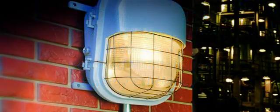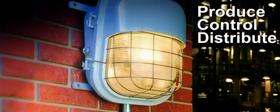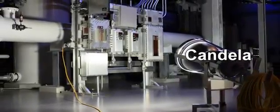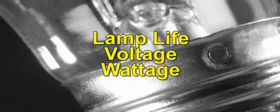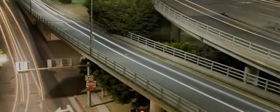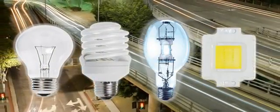In summary, light is produced by a luminaire. Each luminaire produces, controls, and distributes light. Light control utilizes multiple refraction and reflective methods to control the candela output that is measured by foot candles and lumens. Each type of lamp will provide a determined expectancy of life, required voltage, and total wattage output. The color of lamps is measured with two key factors, color temperature and color rendering index. The four predominant lamp sources are incandescent, fluorescent, HID, and LED technology.